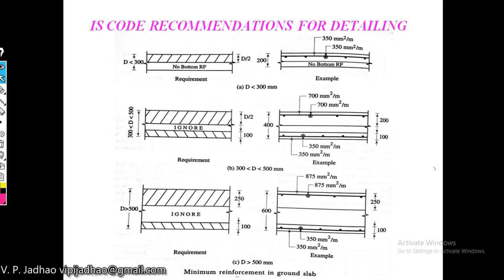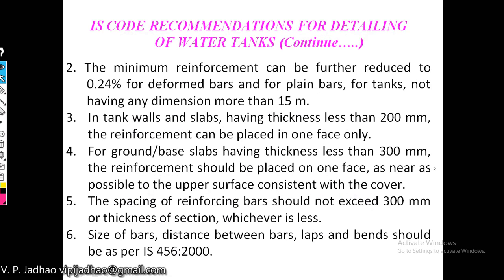Then the size of bar, distance between the bars, and lap and bends should be as per IS 456:2000.